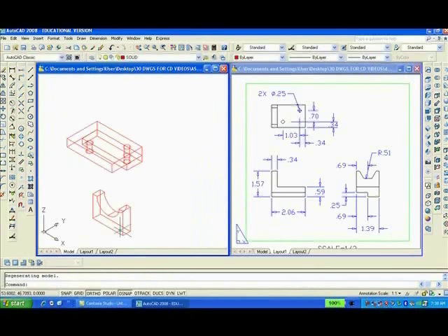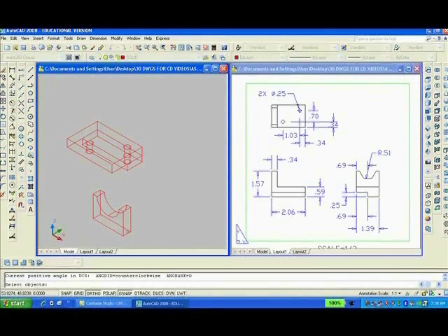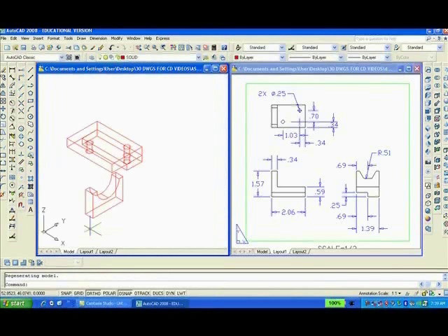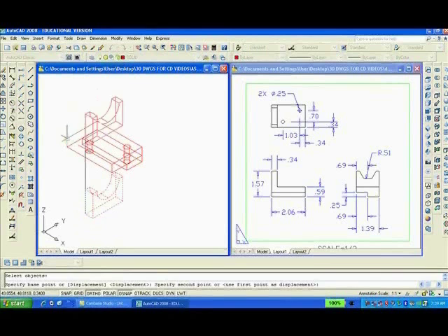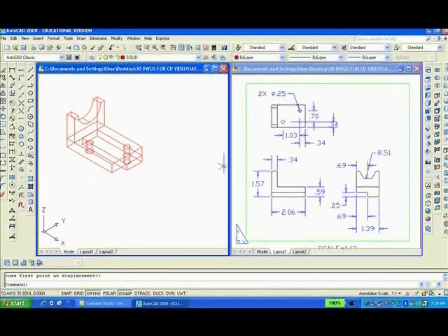Looks like we'll have to rotate it again. 3D rotate this object, take it here. This time I'll click the blue axis, type 90 again. Now I can move this object from here to here and union it all together, and hopefully it'll look right. And I guess it does.